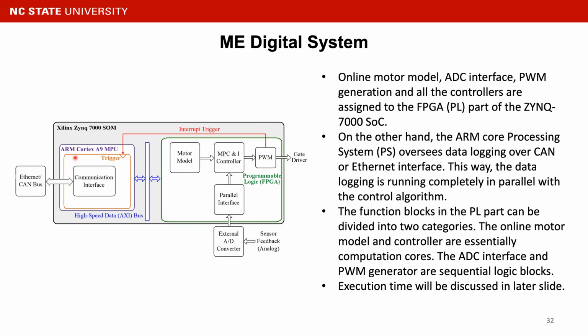The function blocks in the PL can be divided into two categories. The online motor model and the controllers are essentially computation cores, while the ADC interface and the PWM generation are essentially sequential logic blocks.